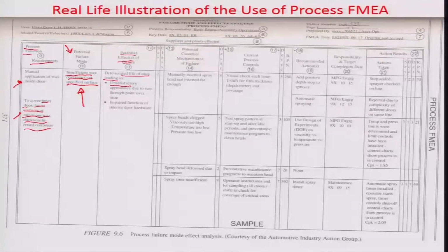There may be impaired functionality of the interior hardware of the door. For example, after a substantial amount of waterlogging for some amount of time, the way that the window regulator moves, placing the window back in the window up position or the window down position, may get impaired because of rust and improper lubrication. Rust actually spreads whenever there is metal to metal contact.